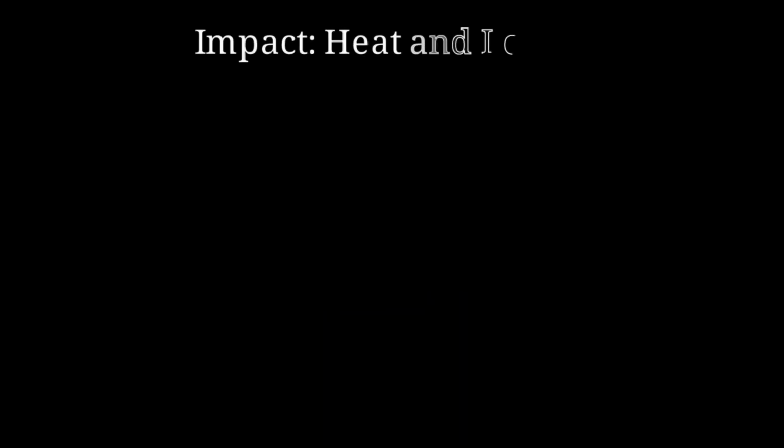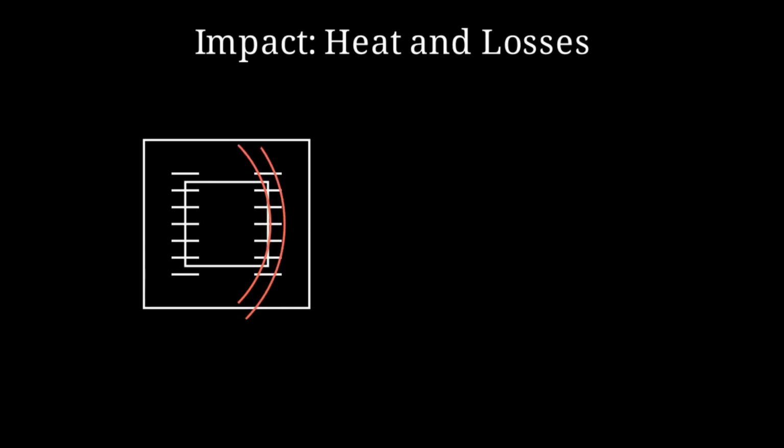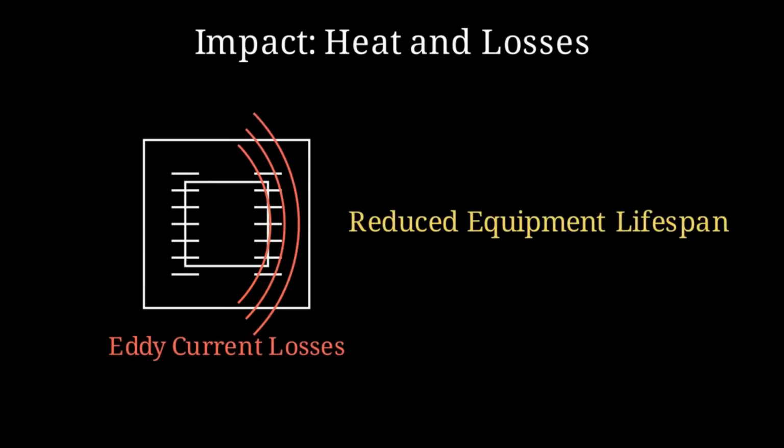High THD causes serious problems. It increases operating temperatures in motors and transformers due to eddy current losses. This extra heat degrades insulation over time, significantly shortening the lifespan of expensive industrial machinery.